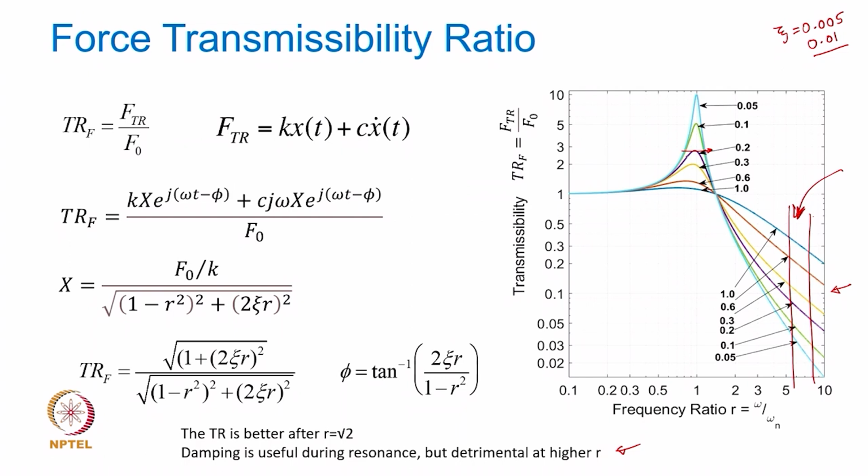But sometimes if you are coasting up rather slowly for some reason, if you cannot traverse through this resonance fast enough, then you might end up generating large excitations transmitted to the base, because you notice that even with 0.05 you are almost transmitting 10 times. Okay. So, you can imagine what will happen with 0.01, right, and then some intelligent damping can be designed.